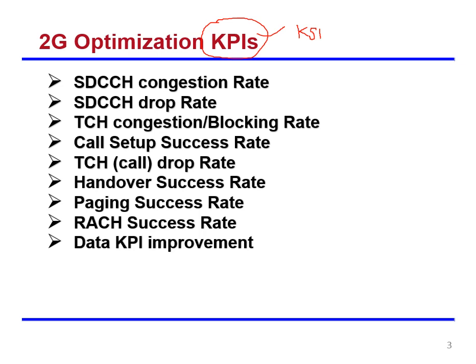This is because of the nature of radio propagation and practical issues. Maybe path losses will be there, or new buildings might have come which were not there during the plan, or there may be disturbances because of seasonal change. Maybe planning was done in a different season, and in the rainy season more water bodies will be there. Water bodies reflect the signal, which may affect the quality of service.